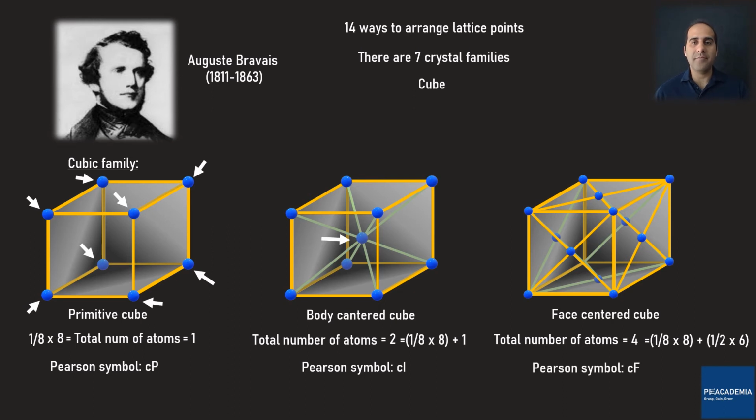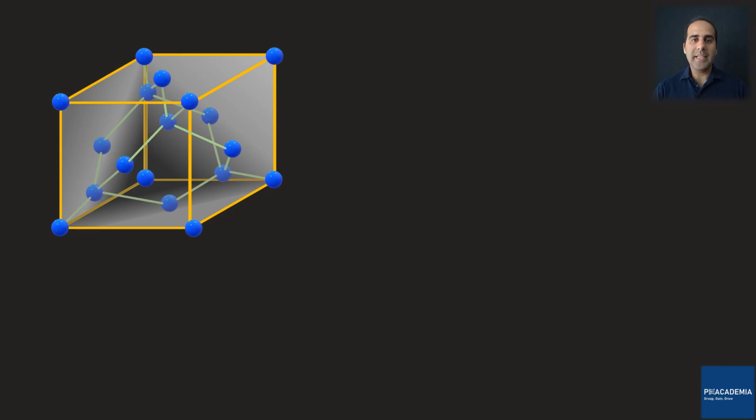Since silicon is the most used semiconductor in the industry, I think it's a good practice to take a closer look at the silicon crystal unit cell. Silicon is crystallized in a diamond structure. Diamond lattice structure can be thought of as 2 interpenetrating face-centered cubes with an offset of 1/4 of the body diagonal.